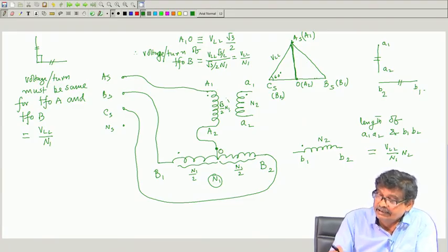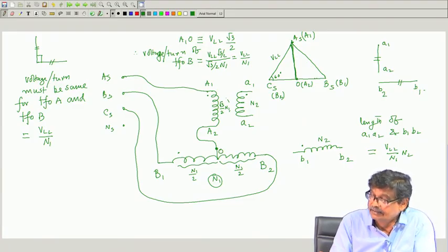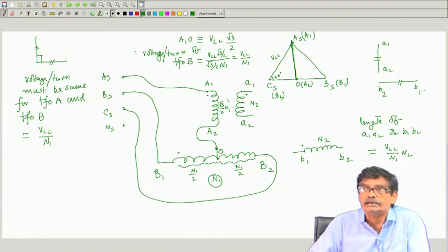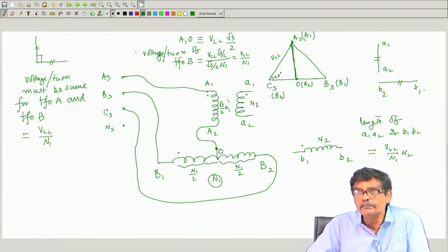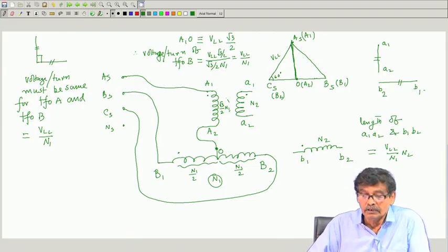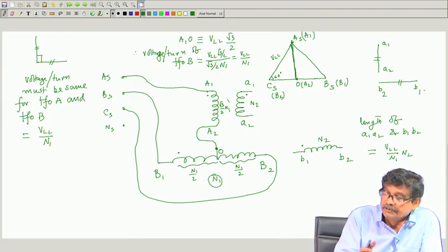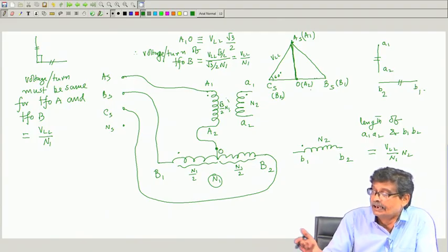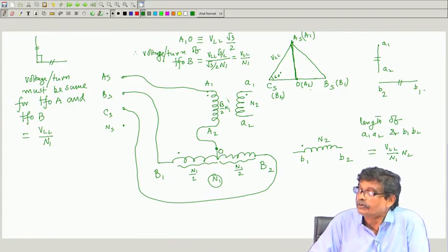So, you see at the secondary coils of these two transformers, there exist two voltages whose magnitudes are the same and which are 90° apart. So, it was a balanced 3 phase voltage, and on the secondary coils, although I have not connected them yet, I get a balanced 2 phase voltage.